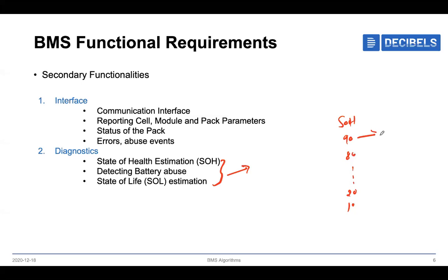So at 90 percentage, how is the cell behaving, which means when state of health is 90 percentage. It is not state of charge. State of charge we can continuously regain. Let's say if you discharge the cell from 100% to 0 percentage, we can again achieve 100% state of charge. But in state of health, once we reach 90 percentage, it will always be in a decreasing mode. We can't increase this state of health.